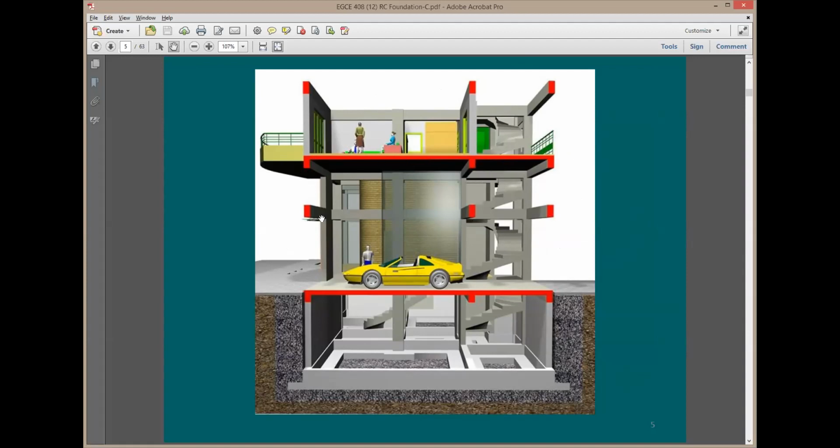Some beams in the middle for some artificial reason, but they don't really provide lots of structural value to our building here. And then we have this concrete slab, which is at the grade level with some beams. Then we have walls. We have columns. You see here, we have a column that runs through, and then at the end here, you have some footings, right? You have some foundation, continuous foundation, sometimes just a pad. A pad means a rectangular pad or a square pad. It is unlike having a continuous wall footing.